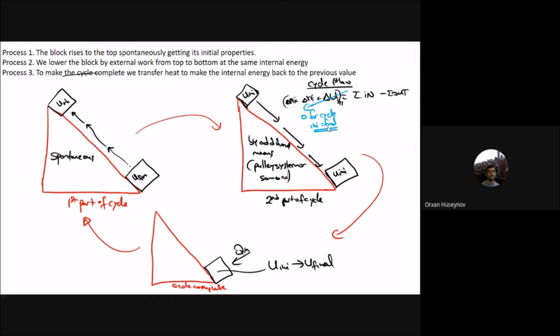Now comes the left and the right hand sides. We have one heat transfer to the process, which is Q in, heat addition to the process. And there is work transfer to the process, because some additional work, by additional means, takes this one from there and puts it back. So work in is not 0. Then I can write this as Q in will be equal to negative work in.